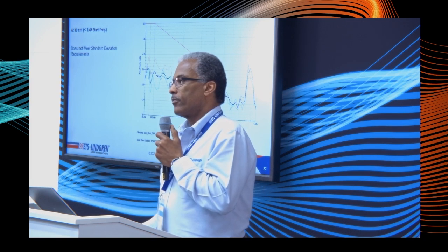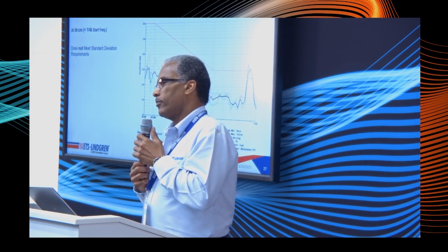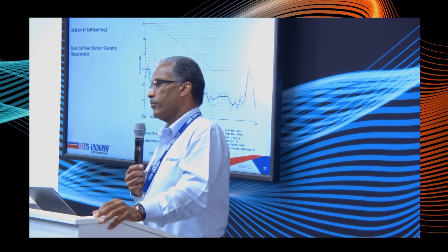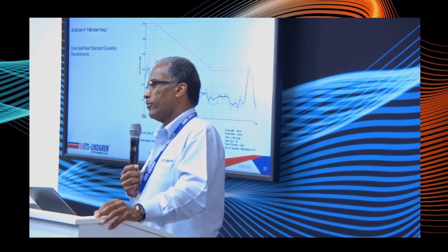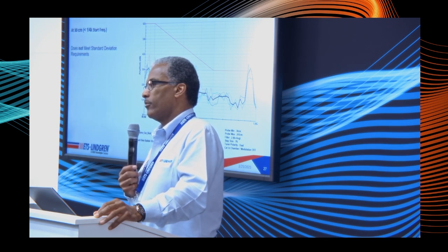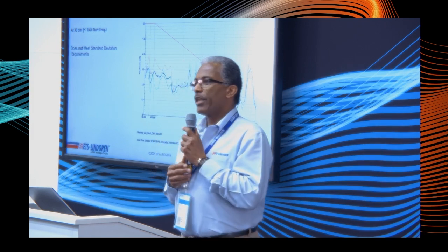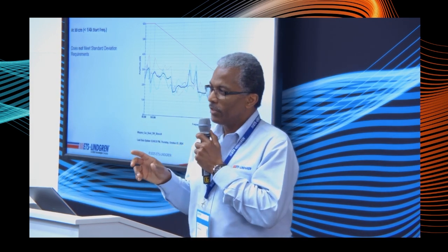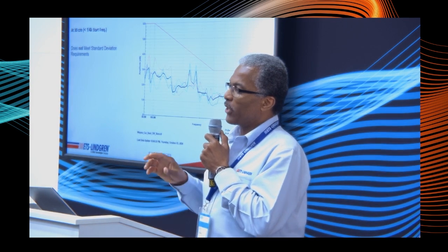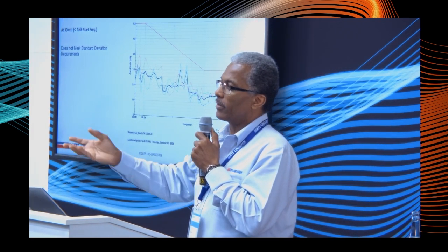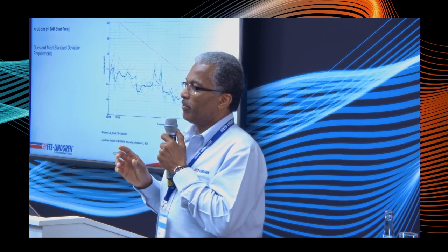And to add one more comment, you kept saying several times that now we have 8 probes and we're making better measurements with more samples. But you also made a comment that physically nothing else is changing inside the chamber. You've got a certain amount of energy going in, and for that energy, you have a certain amount of field that exists. Just because we're taking more measurements, does that mean you're going to get a better chamber or not a better chamber? Well, theoretically yes, and theoretically no, because the chamber environment's not changing. All you're doing is sampling, so you have better statistics. But the environment's not changing.